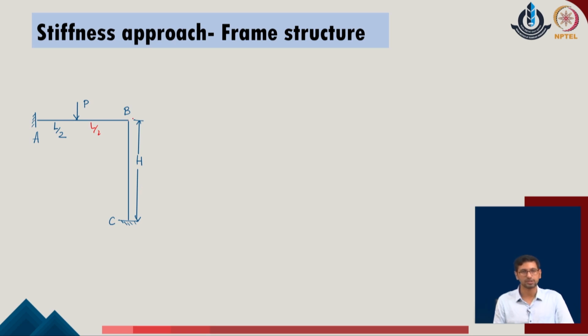Now, as a first criterion of the given system, we realize that it has three joints: joint A, joint B and joint C. As joints A and C are fully restrained, we understand that there is only a possibility of deformations coming from joint B in the given problem.